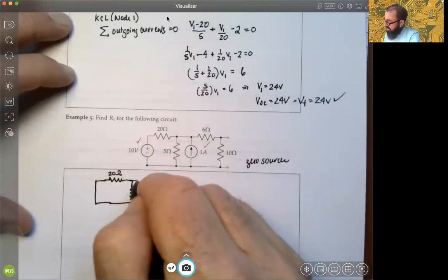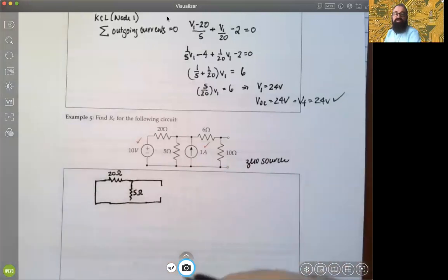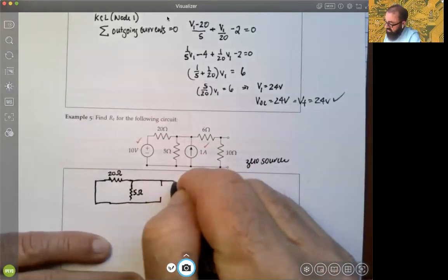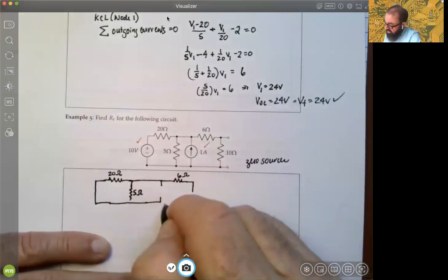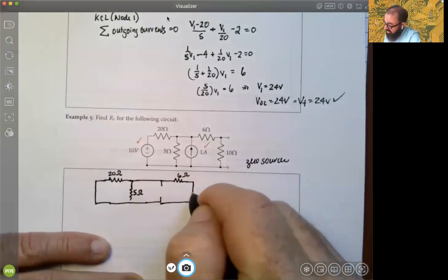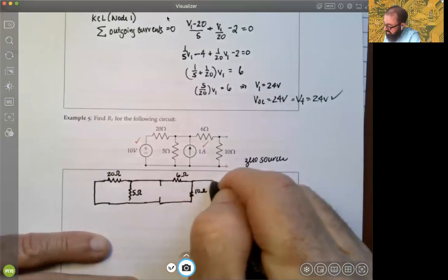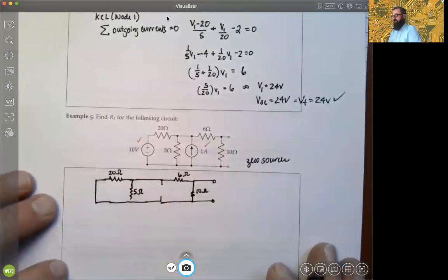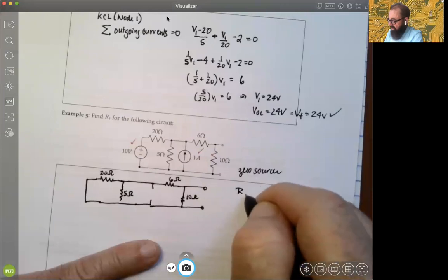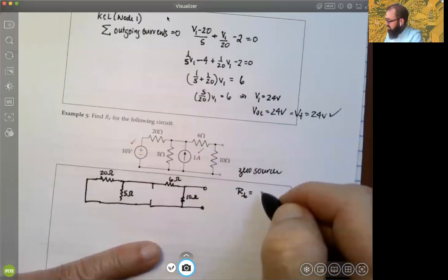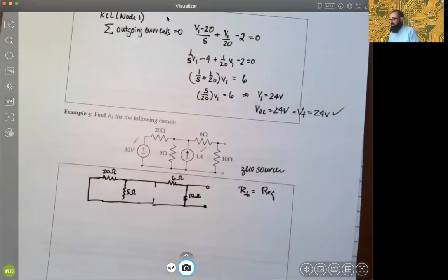And continuing on, excuse me, we have an open circuit, of course, nullifying out that current, but then we have another resistance, 6 ohms here. Coming down over here is your 10 ohm resistance. And then the open terminals there, okay, right? So remember, when you're zeroing sources, your target is that the Thévenin resistance is the equivalent that you will get from what's left, okay? That was the strategy, right?